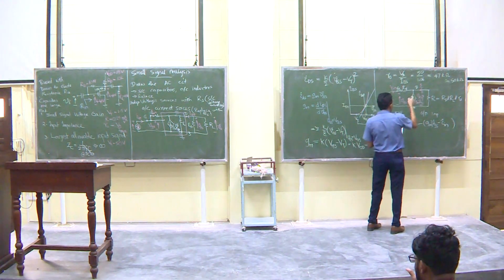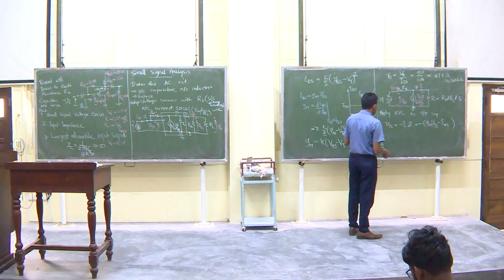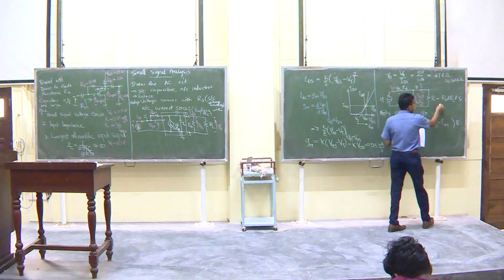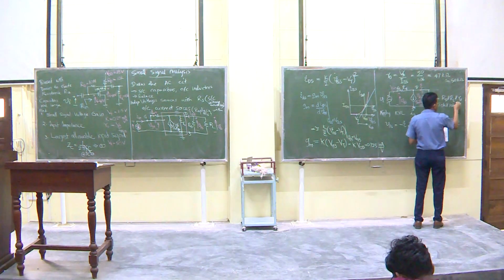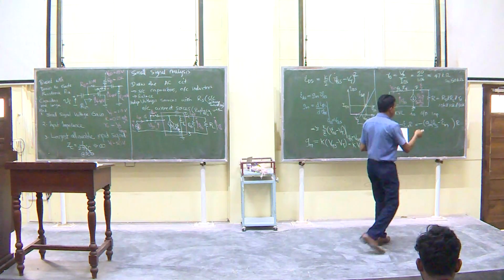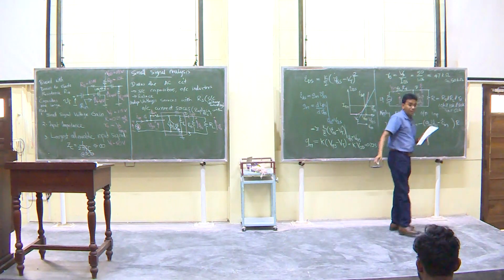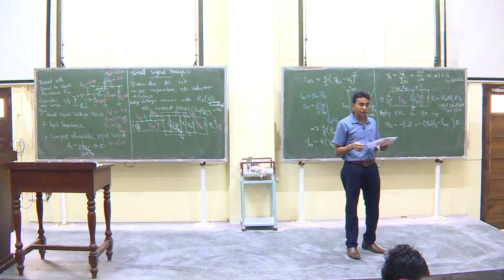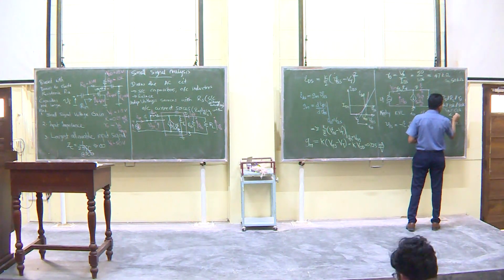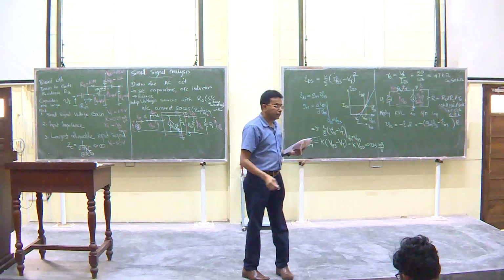Sorry, this is equal to this minus that, right. So you have that times R. R is this thing here. R, this value, is basically 10K parallel 10K parallel 50K. If you want, you know the parallel combination of this and this is 5K. It should be somewhere around 5, but if you calculate this, the R value will be equal to 4.5K. If you want to keep that 0.5, you can do that, right?